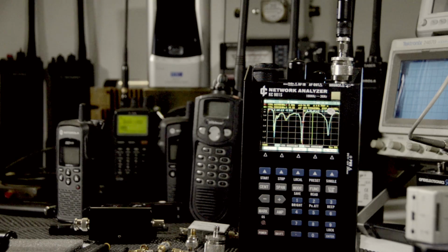However, 1/4 of that, or 250 milliwatts worth of that, is simply being reflected back into the transmitter, where it's being absorbed by the transmitter and re-radiated simply as heat, but that's a loss. So your effective output is only 750 milliwatts.